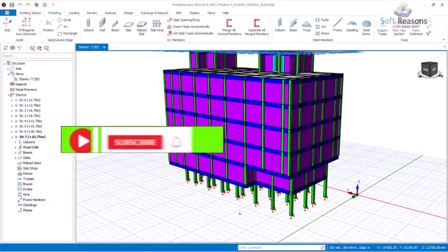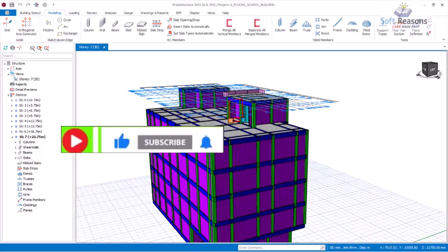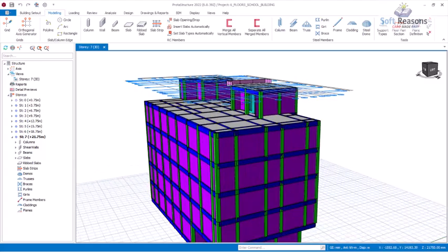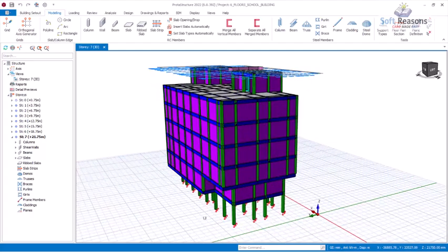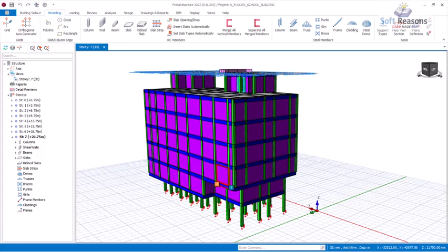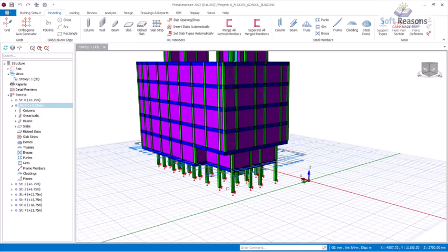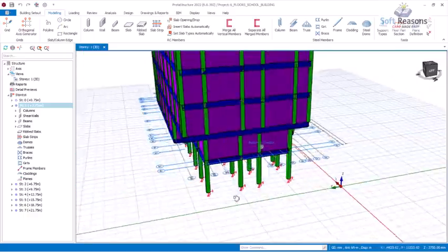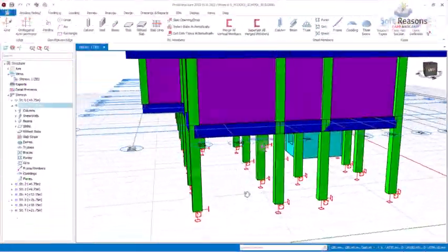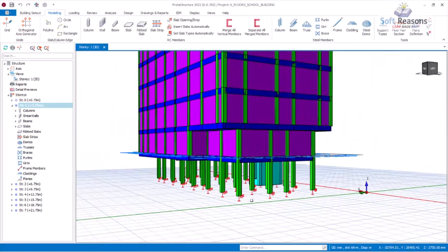Now if you notice, the green line is at Storey 7, the last floor. If you want to carry out an economical design of a structure, you have to start from Storey 1. If I double click on Storey 1, you see the green line moves to Storey 1. In the process of carrying out an economical design, you should have paper so you can take down some important points which I will be explaining to you shortly.